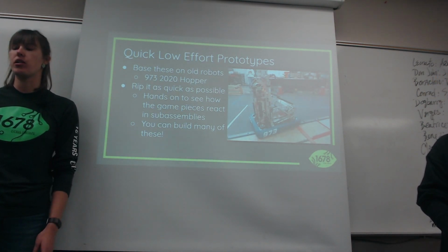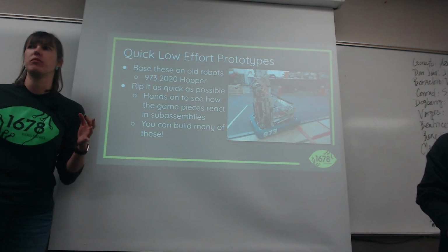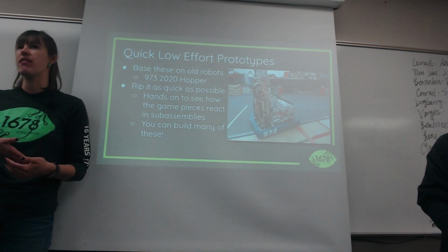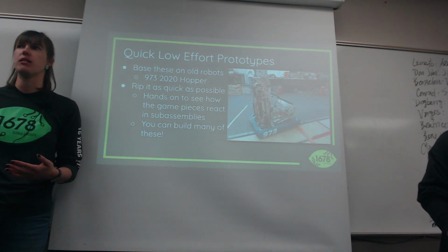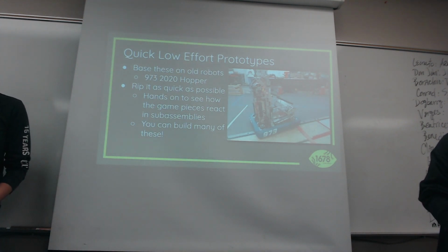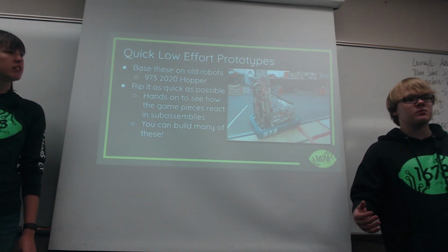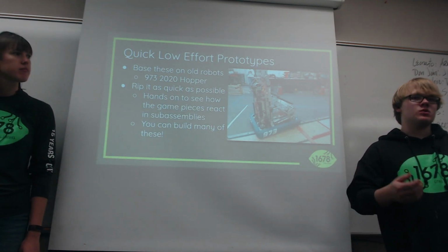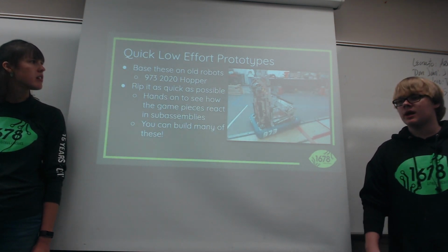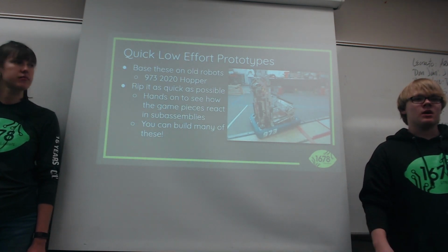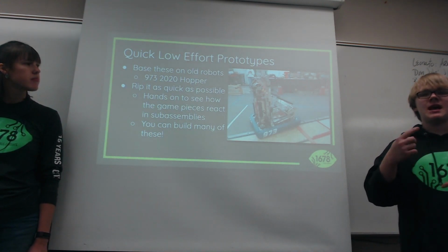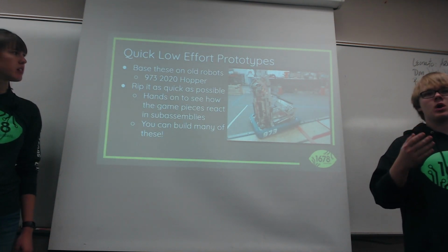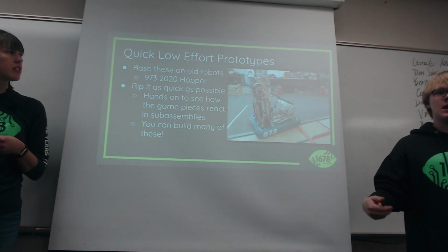And if you have more than one idea that seems like a valid way to go, if you don't know between A and B which one's going to be better, then just do both, because these are really low effort, so you can quickly process and pick out what works and what doesn't work. Like Jen was talking about, these are really not polished prototypes. You don't really need any machine other than 2 sheets of plywood and a drill. And if you want to have them connected, you can just cut pieces of 2x4 and use wood screws. You're basically drilling a hole, putting a shaft on it, and then you can power it with that same drill just to see how those game pieces are going to interact in these sub-assemblies. Because you don't really know how a handoff is going to work or how a shooter is going to work until you actually put stuff together and see how it functions.